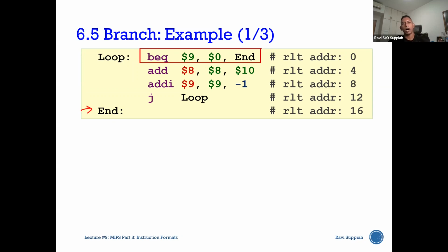Now, after I fetch this instruction, the moment this instruction is being executed, I will immediately go to the PC+4, which is the next instruction. So the PC+4 by default is always the next instruction to be executed. Now, if I am going to take the branch from this line, how many lines away am I to the N label?